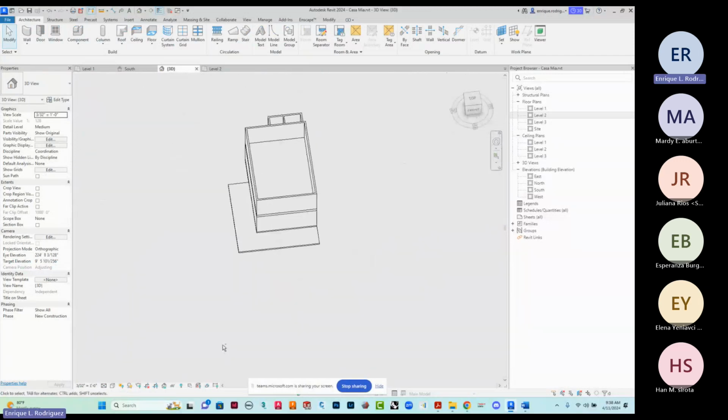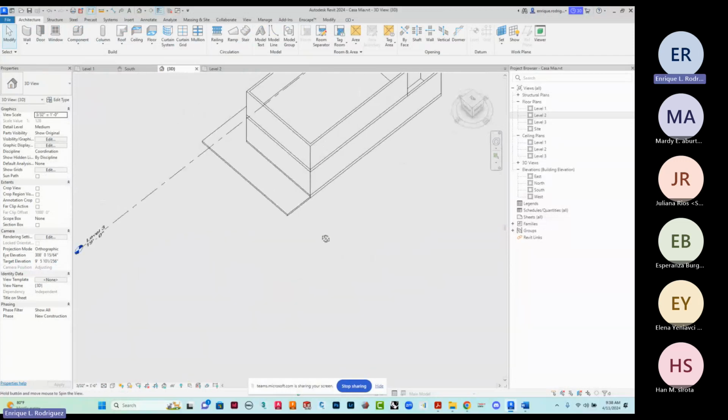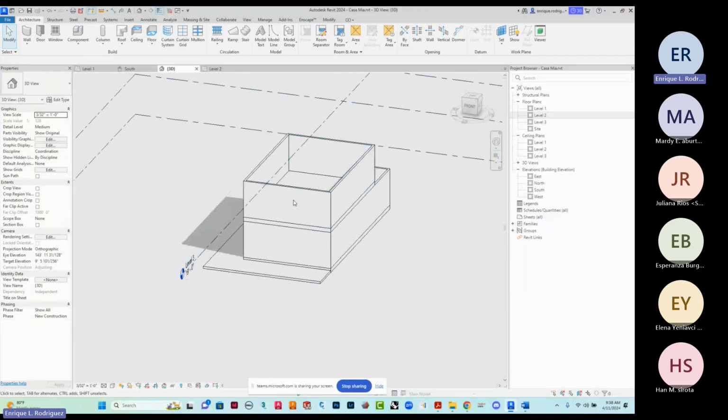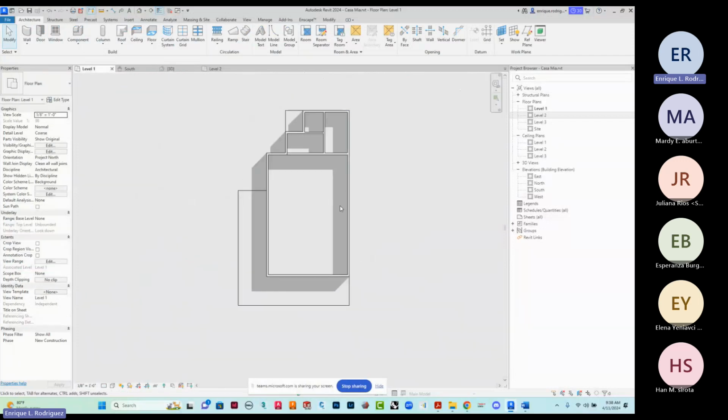Any questions so far, guys? What we're doing? This is pretty basic for beginning the layout. So what I would do at this point, if you want to continue further with the project, is start laying your inside walls. Remember, the exact location of the walls are always movable, okay? So if you don't have a dimension, let's just graphically get them done. The things that you should definitely pay attention to is what level you're drawing them, what height they are, if they are attached or dependent on a level, which I suggest. Make sure you worry about the offset, etc.